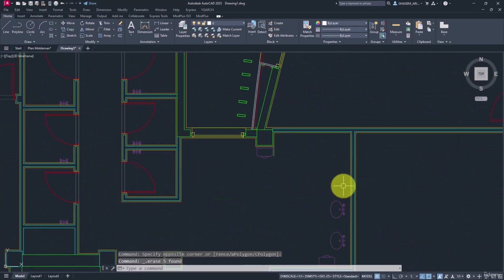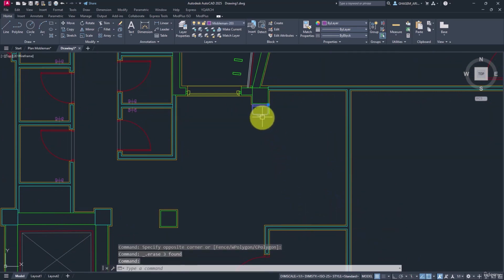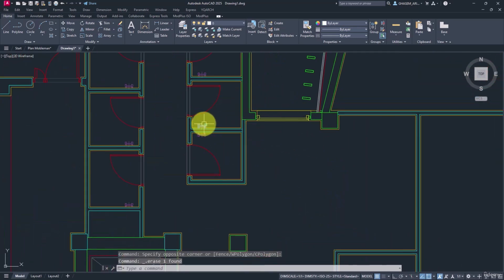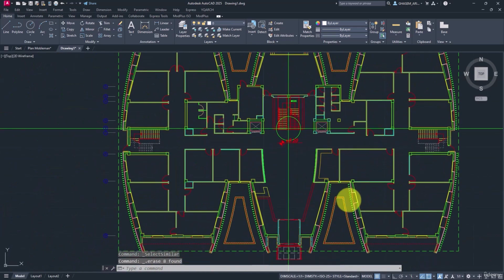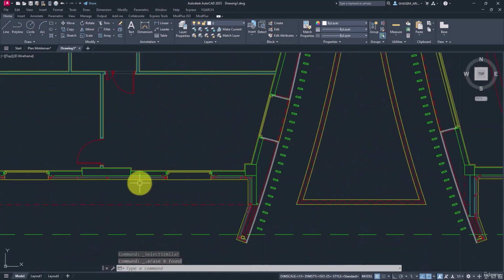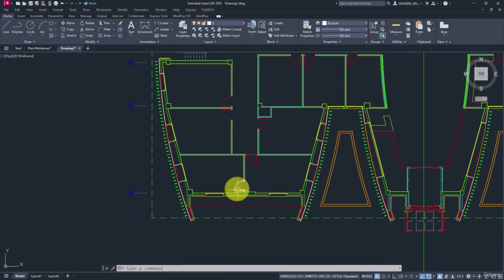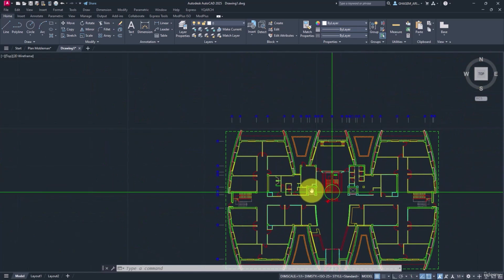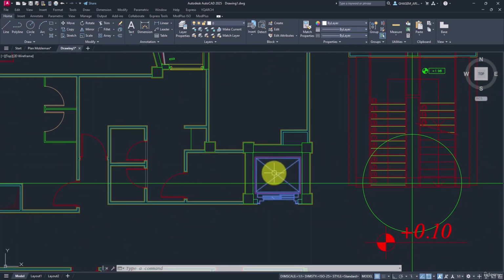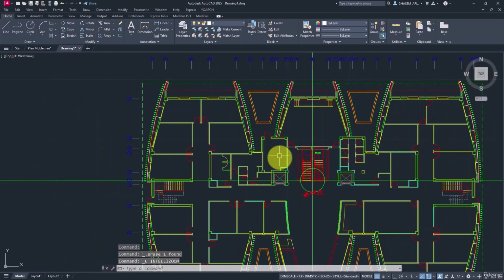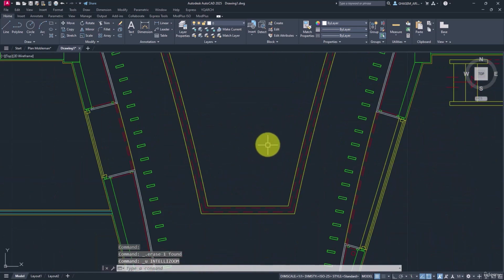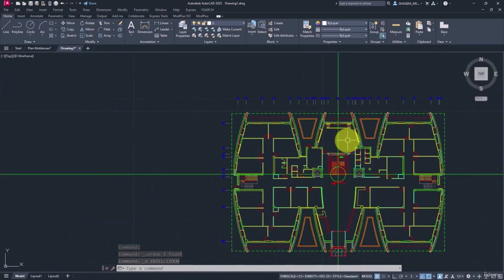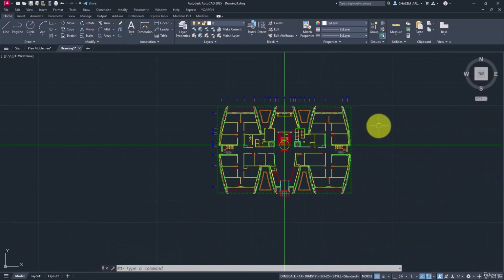However, these are the decorative elements that we got as a family, and we're going to model them as a family. And select similar to delete. Then let me check others. And these are very important to be deleted in order to optimize the file. I keep the box of the elevator. Okay, right now the file is ready to be exported.